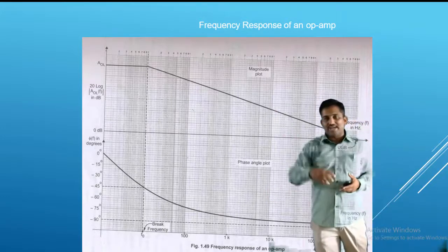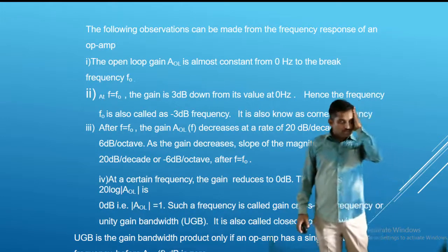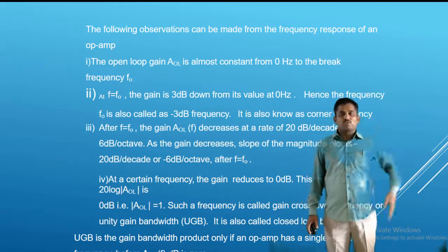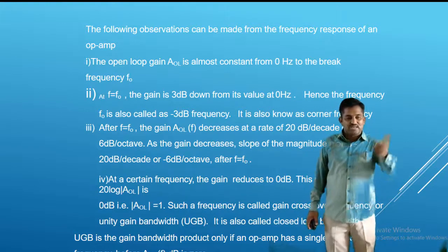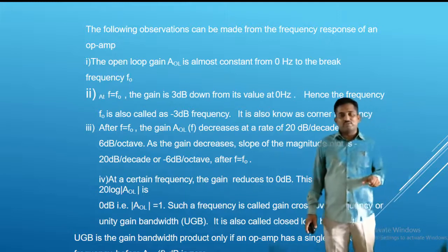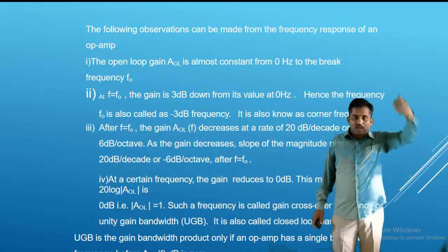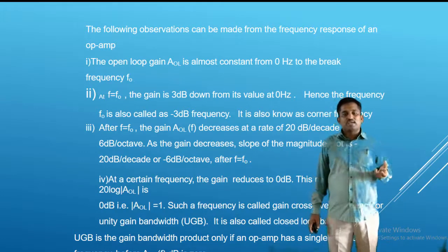You have to bring that unstable system back into a stable system. Here I told you about the gain crossover frequency as well as the phase crossover frequency, and also I explained the bandwidth. Now these are all the things which we will know from the phase angle plot.